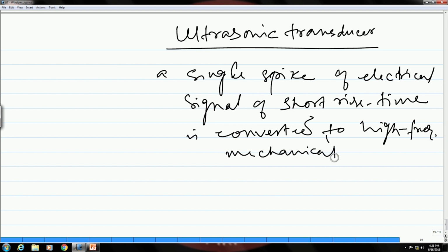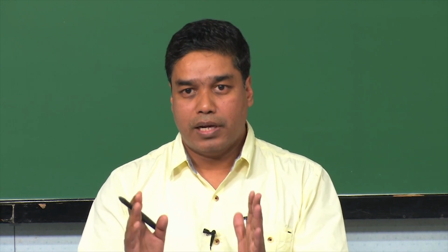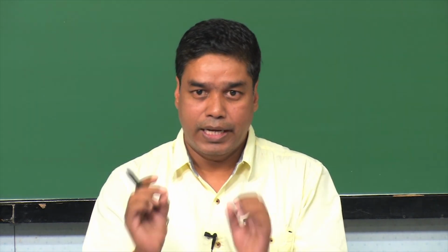So, this is the device which converts an electrical signal into mechanical vibrations, and that, as you may all know, is called piezoelectricity, right. So, the main component of an ultrasonic transducer is a piezoelectric element which converts an electrical signal into mechanical vibration or ultrasonic waves.